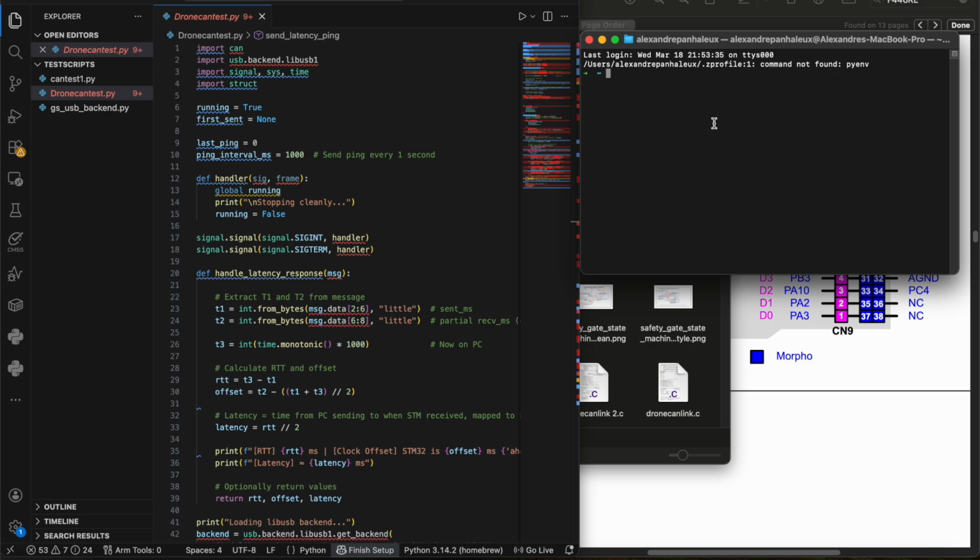So that is the goal of our project. It's really to create a CAN node that is gonna read the sensor data via I2C and publish it via CAN. So CAN protocol, it's a multi-node communication bus, meaning that we can have different systems publishing over CAN, but also reading over CAN. So it's widely used for drone. There is even a version of CAN that is DroneCan that is specifically for drones. So yeah, it's really the purpose of this project.